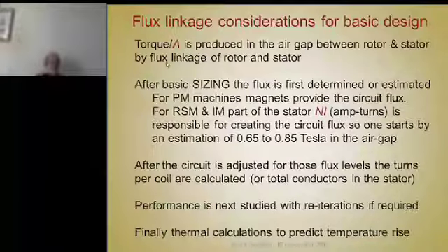Now you've got to adjust the circuit to carry that flux for all three machines by figuring out what the cross sections are, and you have to balance that with the cross section you have available for copper. Once you know what the ampere turns are, you know what the current is, how many turns, how much space you've got, and what the current density is.